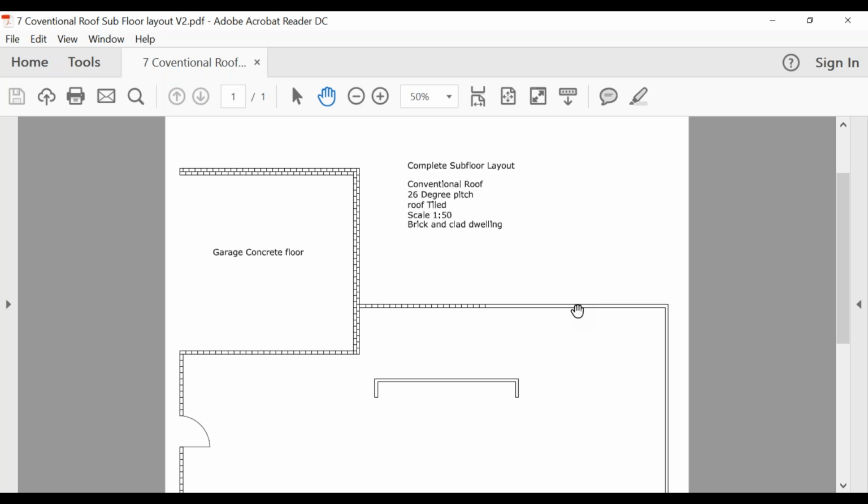Okay, Valavan, I'll just show you what I've done, mate, so you're not sitting there waiting for ages. This is how I would do it. The first thing I've done is start to draw in where my bearers are going to go. The bearers always go the lengthways of the building. So I'm going to put one on the external, right along that wall there. Can you see my mouse when I'm moving it, Valavan? You can see the little hand? Yeah, I can see the hand.